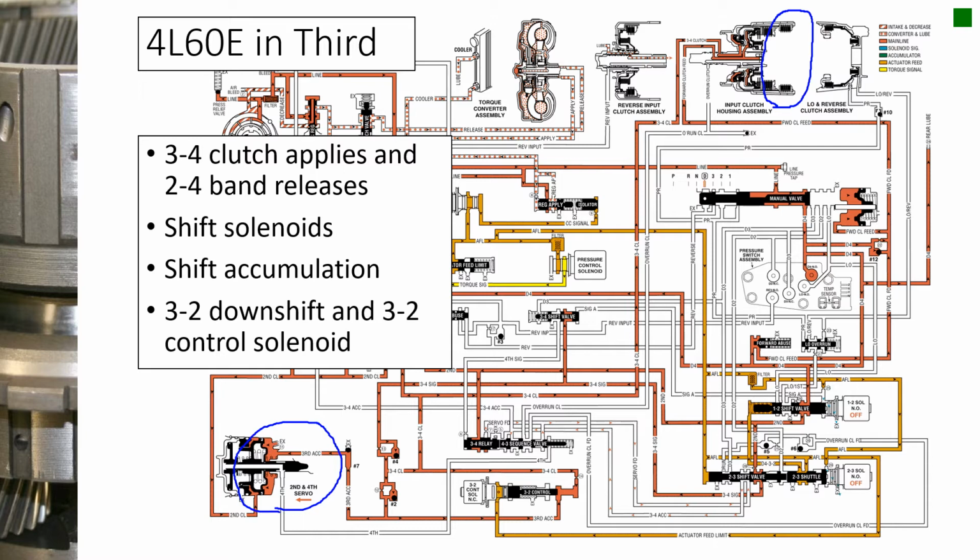This is, for the most part, one of those transmissions, except for the 3/2 downshift or the 2/3 upshift. You have to synchronize those. And we'll look at how they do that here on some of these slides.